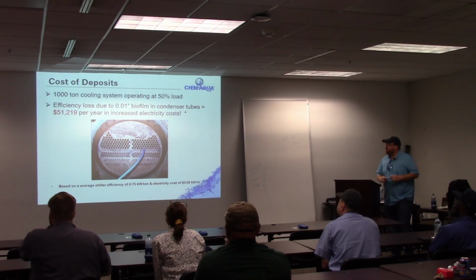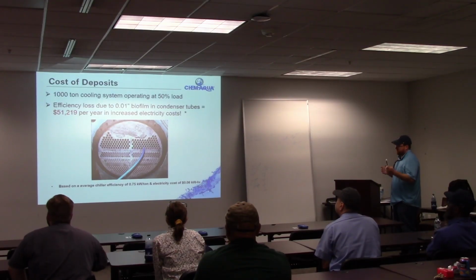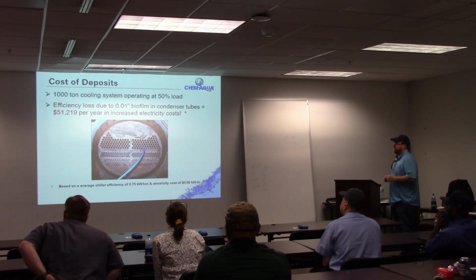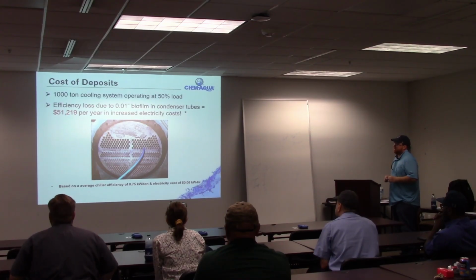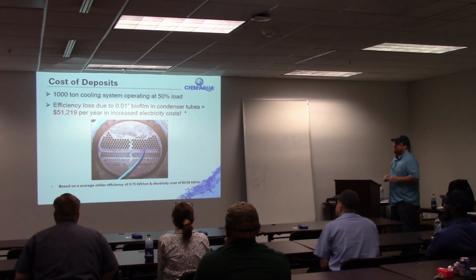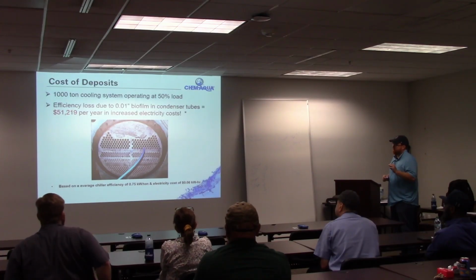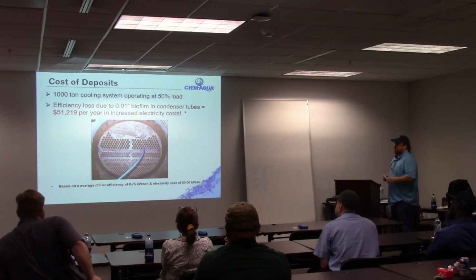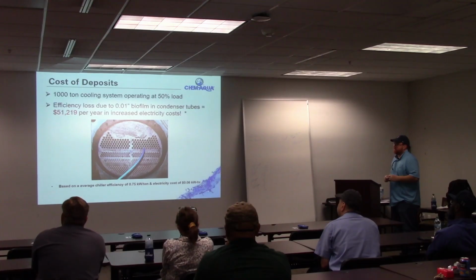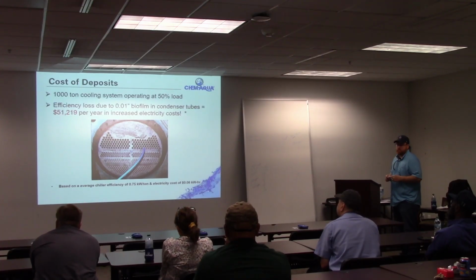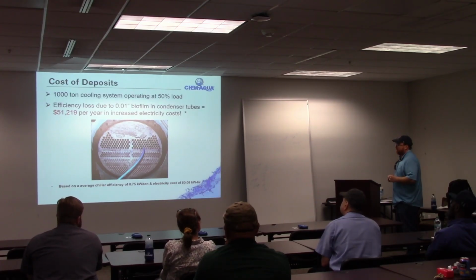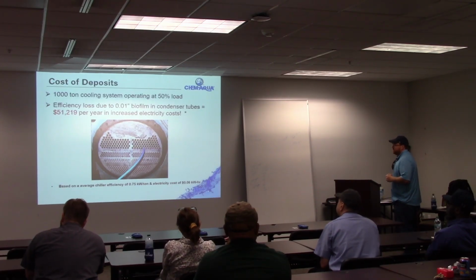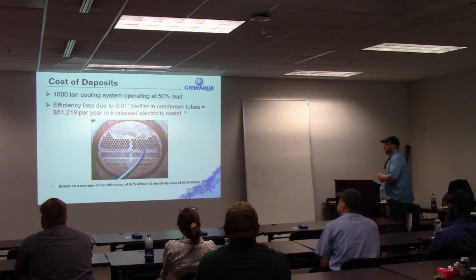All right, so in addition to that, just to kind of continue to illustrate it, a 1,000-ton cooling system operating at 50% load, a biofilm of just 0.01 inch in thickness, under those system operating conditions, can increase your electricity cost over $51,000 a year. So it's really, really important to make sure that bacteria levels are kept low.